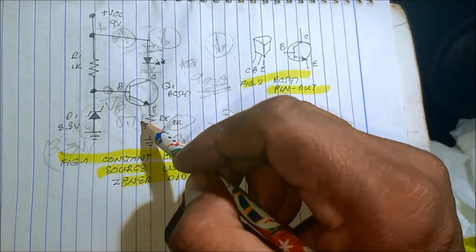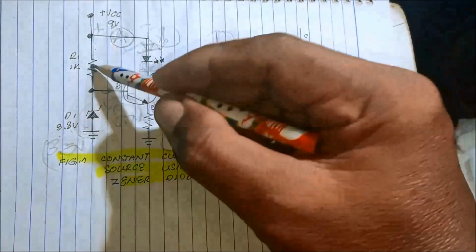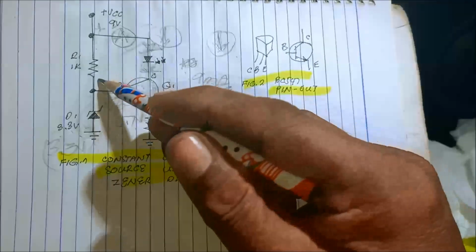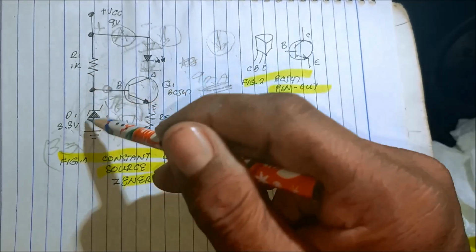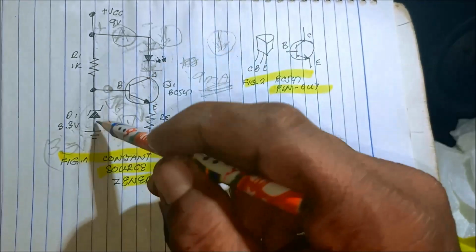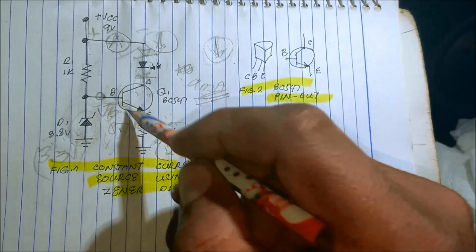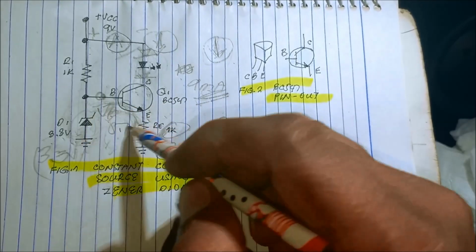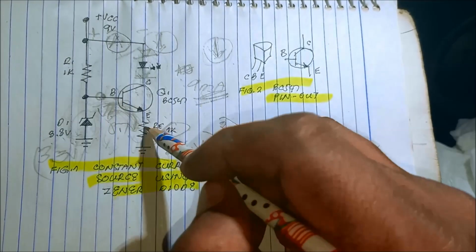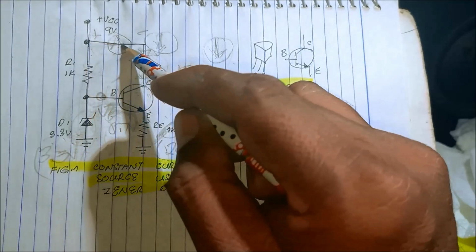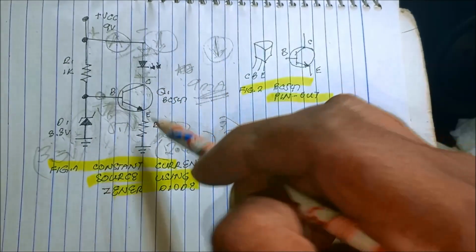Because the current flows here, which is not actually the current, voltage at the base. These two are known as the voltage biasing of the transistor: the 1K and the LED. So it functions. The transistor operates because there is now a biasing voltage at the base to emitter, causing the current to flow from the 3 LEDs and then collector to emitter, then the resistor.